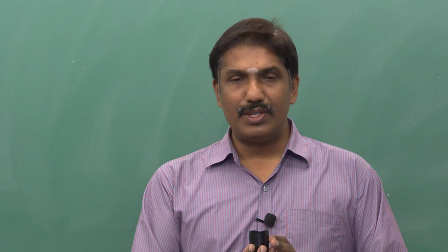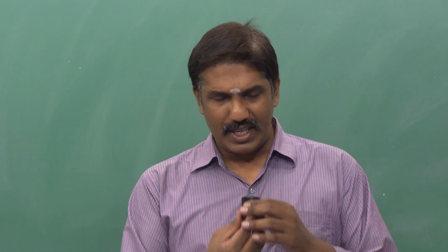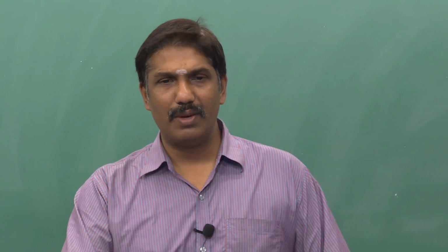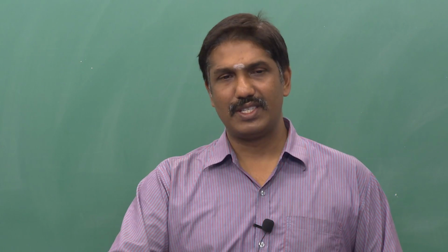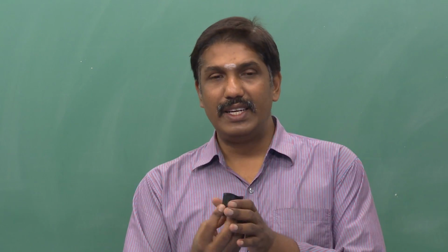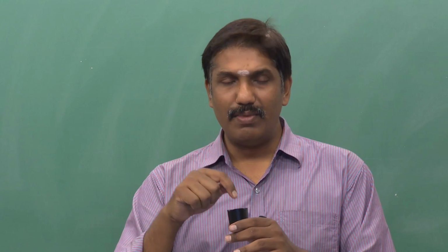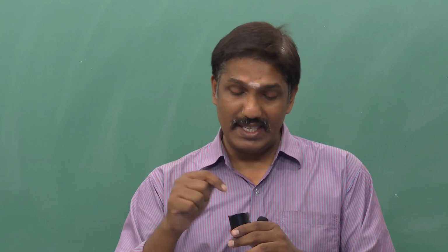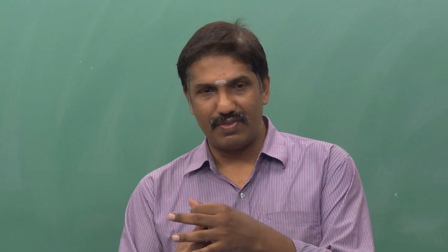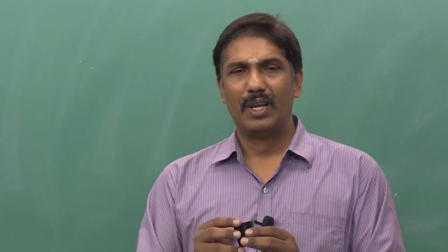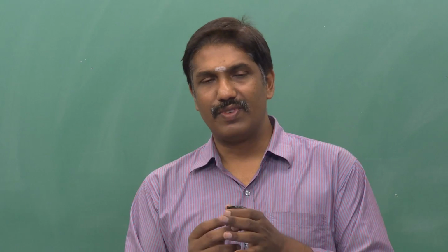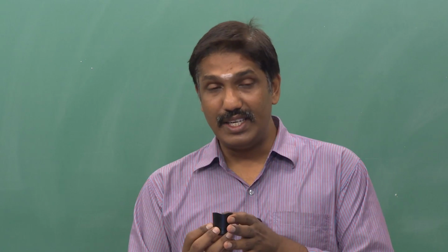Functional means the part where a certain function is expected, and I am more worried about dimensional accuracy, finish, everything. A non-functional surface is a surface where I am least bothered about the dimensional accuracy and the finish. For example, you take this component, I need a smooth surface, I need a hole, but I am least bothered about the dimension of the hole or the internal finish of the hole. I am worried about the external finish of this product. So, this is a functional surface, and this internal surface is not such an important parameter for me. Those internal surfaces are called non-functional surfaces, and functional surfaces are wherever I need to maintain a dimension and smoothness.